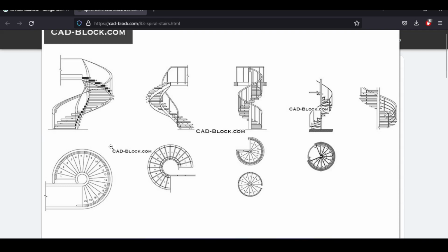And the last type is maybe a staircase that is surrounded by walls on both sides, meaning that each step is carried longitudinally and transversally. Of course, you can have combinations of those. For example, you could have one staircase like this, but with a central column carrying the staircase in the center here. Of course, there are multiple combinations for those staircases. I will try to cover the basic ones and leave the combination idea to my dear viewers to investigate themselves.